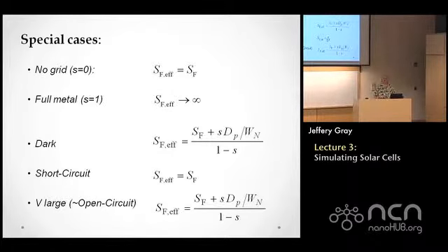Recombination at short circuit in a good solar cell really isn't typically all that important. And if you model it with whatever it should be near open circuit voltage, you'll do a pretty good job. So you don't really need to use your analytic model with a lot of different values. You can say, well, this is characteristic of the front surface, and that's what you'll use.